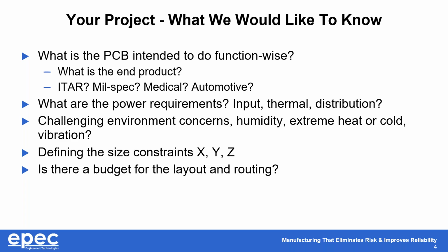PCBs are intended to function, so what is the function, and what is your board intended to go into? What is your end product? Is it going to be ITAR, military, medical, automotive, or domestic? What are your power requirements, input, thermal, distribution, and what is the layout for those items? Challenging environmental concerns such as humidity, extreme heat or extreme cold, vibration, or a combination of those. Defining the constraints of the board, X, Y, and Z: your total length, total width, and total thickness. Is there a budget for layout and routing, and where are you with a timeline for that?